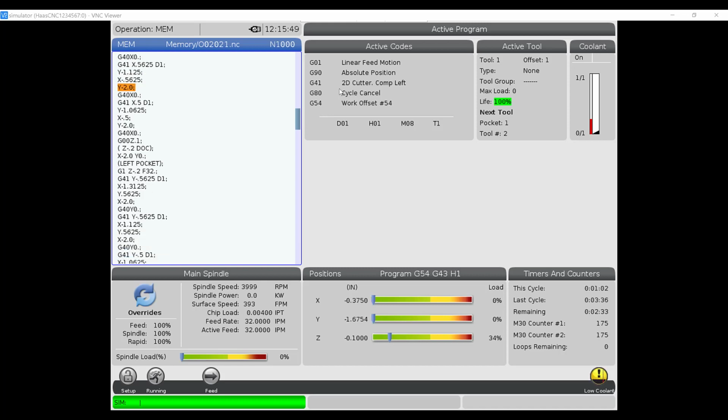All right, so hopefully we will see a movement to X minus 2. We'll go up in the Z. We'll go over. We'll go down again to 0.2 and continue cutting. So we'll watch this go again. And it's rinse and repeat here, just doing a different depth of cut, roughing out each of those pockets. Cancel comp, and again, you can watch the machine work through its motions.